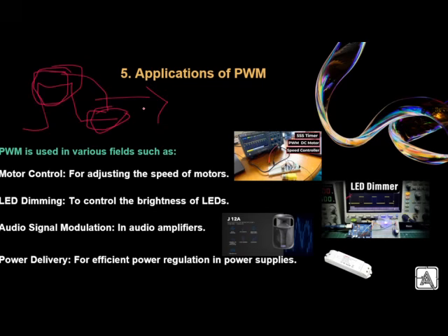Obviously, if we are mixing these two, then the light intensity will not be as high as in the on state. It will be somewhat dimmer. But you will not perceive light in the off state. You will continuously get light, depending upon the duty cycle, obviously. If the duty cycle is more, then the intensity of the light will be more, and for a longer duration you would be able to see the light continuously.